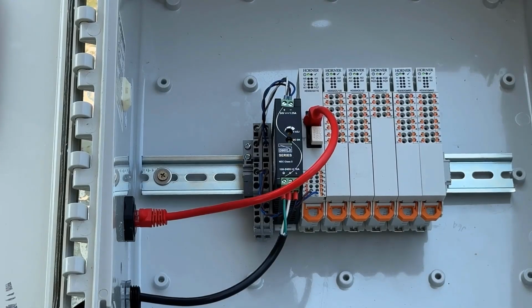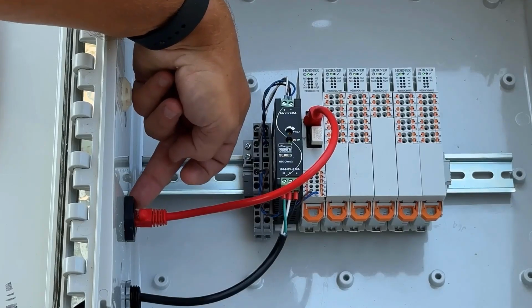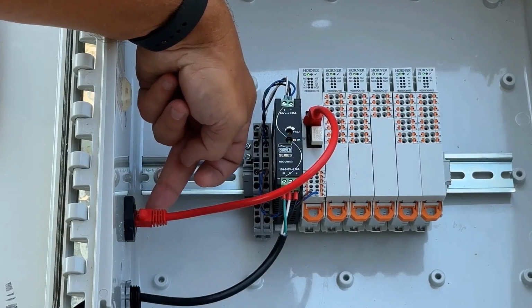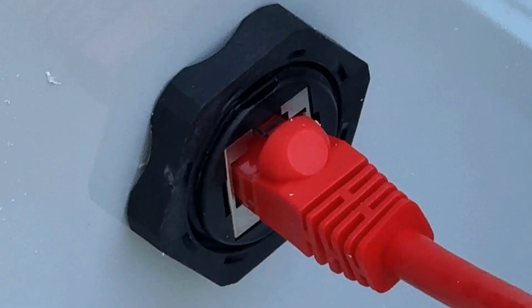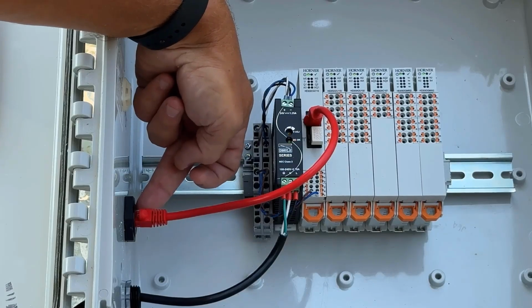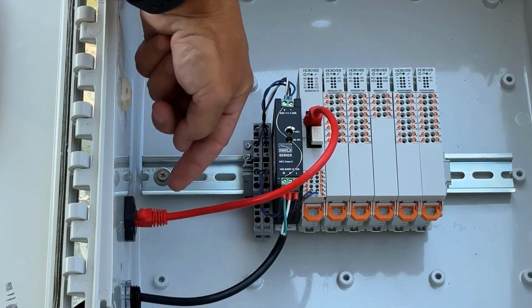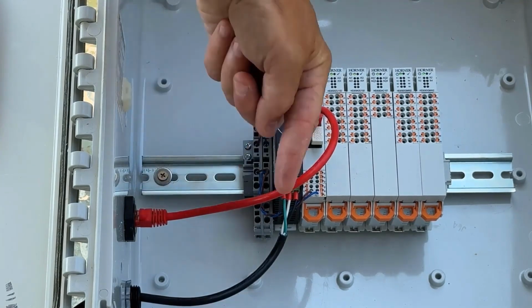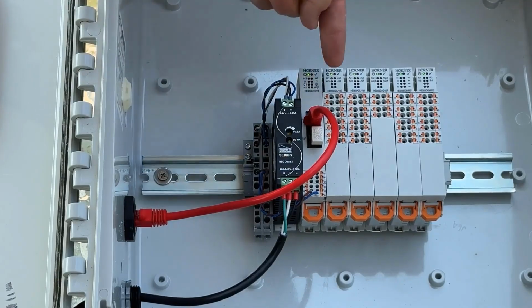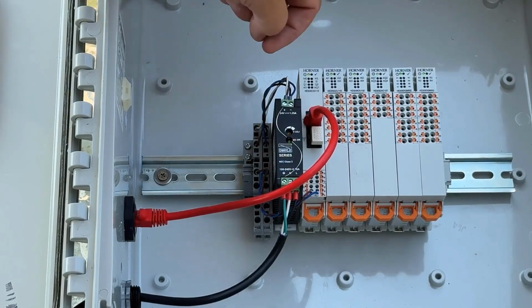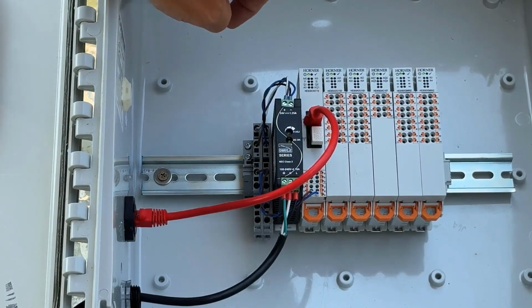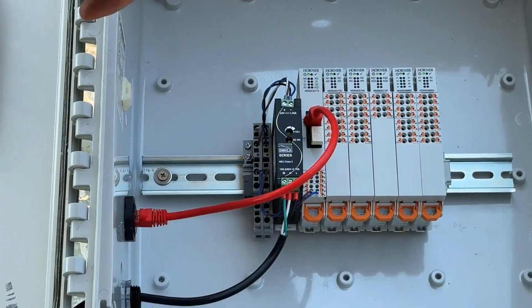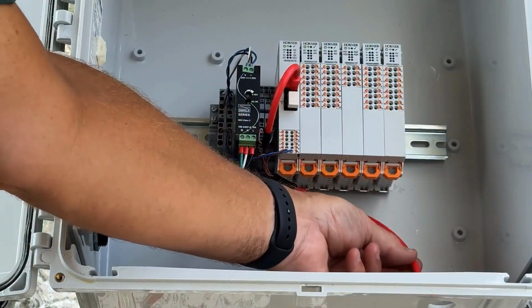For this remote panel, we are using Cat5 or Cat5e wiring from panel to panel, and we happen to be using a bulkhead connector that has RJ45 on both sides. So on the outside of the panel, we have an RJ45 connection. On the inside of the panel, we have an RJ45 connection. So we have got a standard patch cable, this time a 1-footer, coming from the bulkhead connector to the OCS I/O base. And once again, we have our terminator plug to make sure this end of the network is properly terminated.